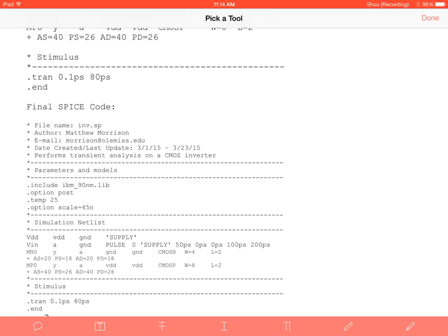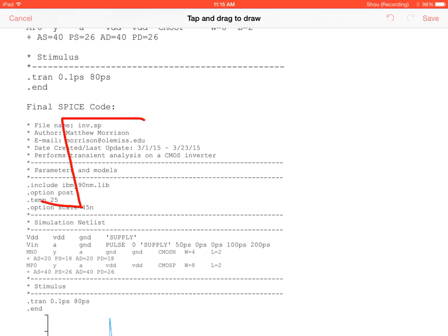So we have an inverter, and we had spikes, right? Why did we have spikes? Because it instantly jumped up. Mm-hmm. And what's physically going on? So this is a good combining concept. We've gone immediately from 0 to 1, so we have our condition where the input goes immediately from 0 to 1. That means, and we have an inverter, so what does that mean on the output? Just from 1 to 0.